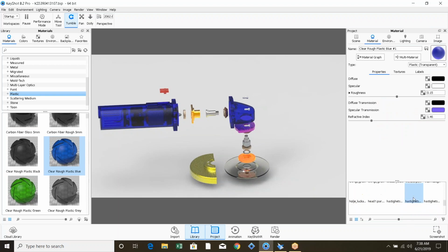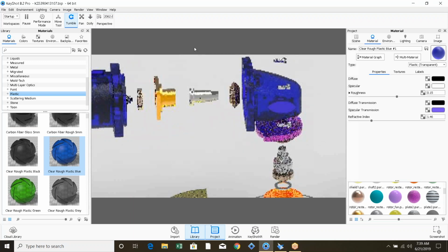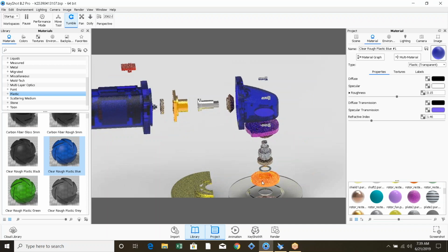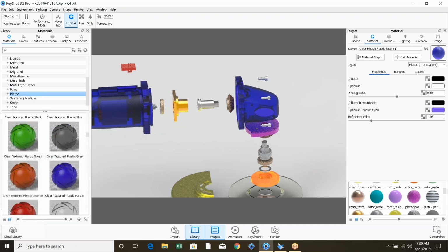because we have a list of materials that came from Solid Edge. That's why I make Solid Edge all these multiple colors. So a lot of times if you change one color, and something like this little part right here is what in Solid Edge is steel red hot, if I have 5 colors and I change one, well, it's going to want to go change all those. So I don't necessarily always want to do that. So that's why I like making different color parts, so I don't have to worry about linking them together and inadvertently changing one part when I'm not meaning to.